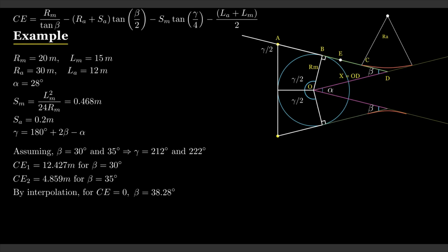After one or two quick iterations, we land at beta equals 38.805 degrees, which we can now use to compute x. The same process applies to the other leg. And again, each side can have its own independent parameters depending on the topography. And that wraps up the theory behind the normal hairpin bend.